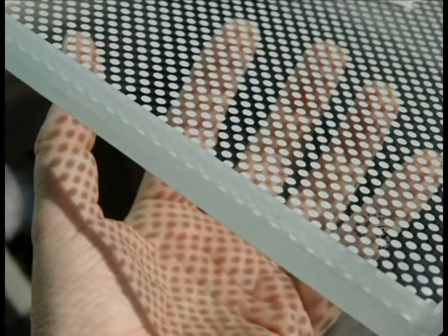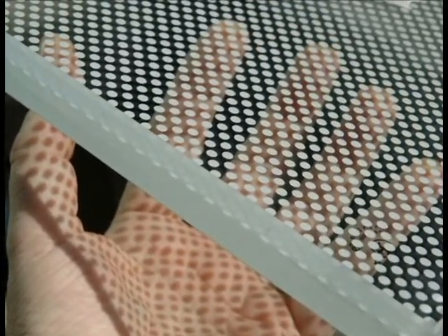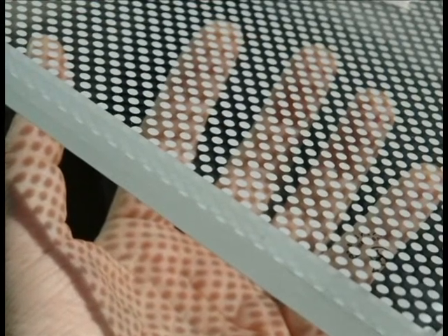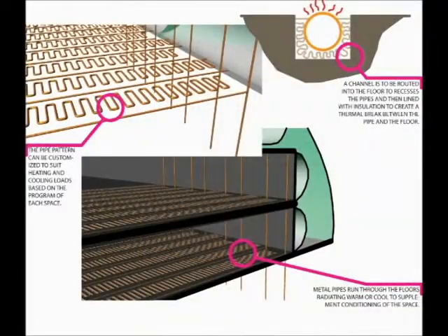From earlier material research, we determined that in order to maximize solar radiant heat gain, the thermal controller would be made of a highly transmissive clear material. Only the north side of the unit is covered with black painted insulation for maximal absorption and minimal obstruction. For the piping, a low emissivity and highly conductive material absorbs and transfers the treated air to the occupied space. This piping is insulated from below to retain the desired temperatures.